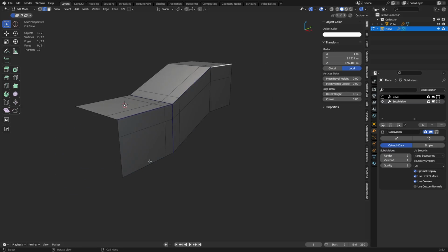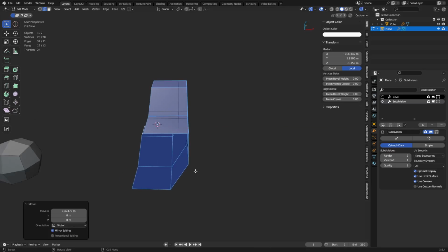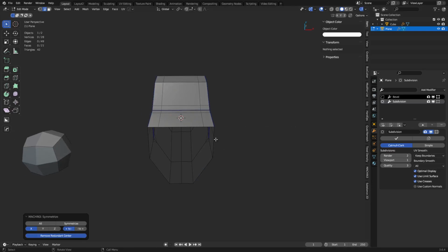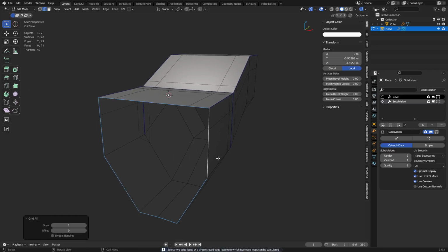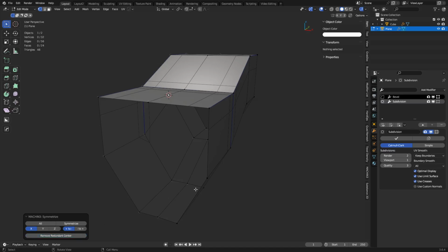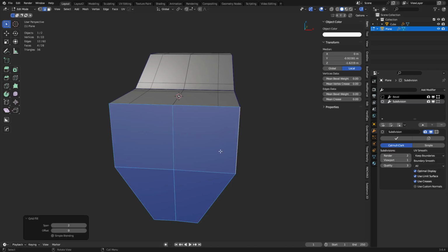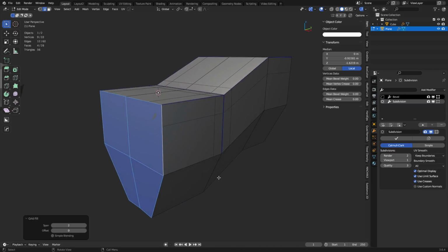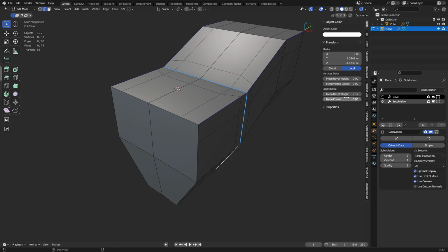So what I mean by that is maybe something like we're working this shape. I'm going to symmetrize it using Mesh Machine real quick and Control F and grid fill. Oops, it's not going to grid fill, I guess. Let's try loop cut down the middle. Turn remove redundant center off with Mesh Machine's symmetrize feature there. So we'll do a grid fill across this. Okay, and so you can see if this is a loop all the way through. We'll set it to 0 real quick and we'll just reset it.